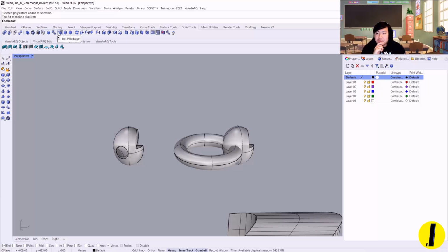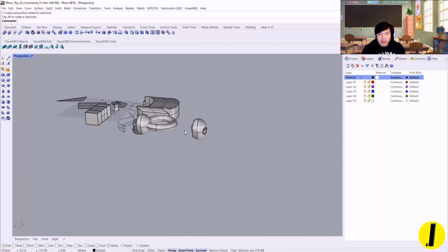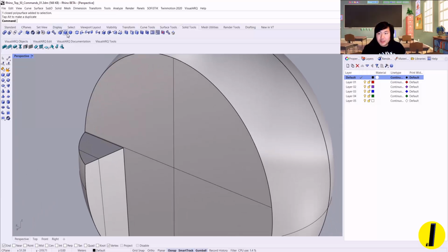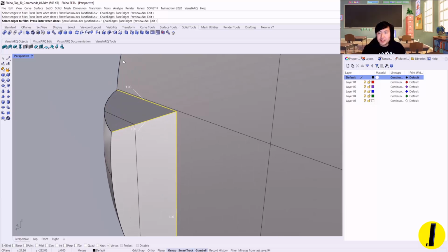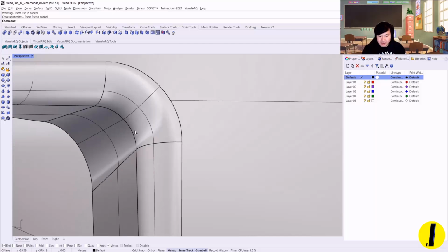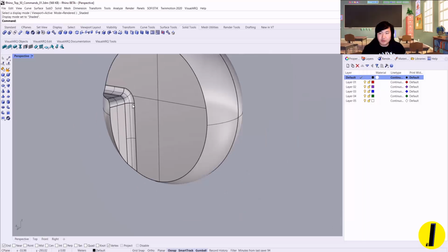But it's not that important. Of course, if you can master it, it's very nice, but perhaps Fillet Edge could be interesting for you. So what I'll do is zoom in here. We can click on Fillet Edge, and when you click on the edge of the joining area of the solid, you can define different radius, and when you define it and hit Enter, as you can see, we can fillet the edge of the solid joint area, which is quite nice.